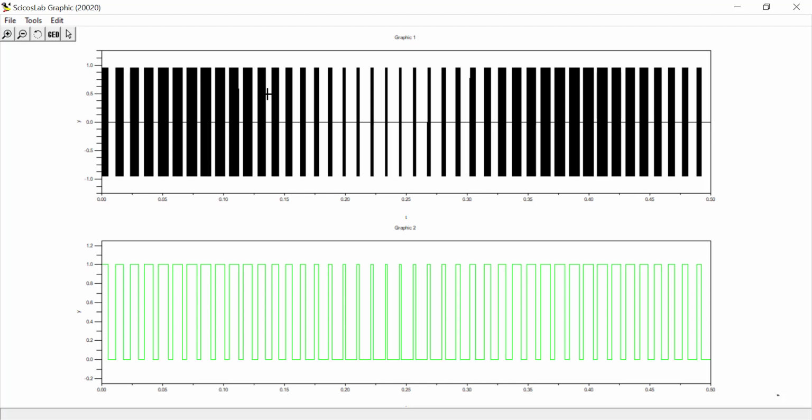the width of the pulse here is directly proportional to the control signal. So it's analog in that way, and then digital in the sense that it's either there or not there, and you can get rid of the noise. So it's a very good modulation technique. It's used for motor speed control, and it's also used for, let's say, Class D amplification for amplifiers.